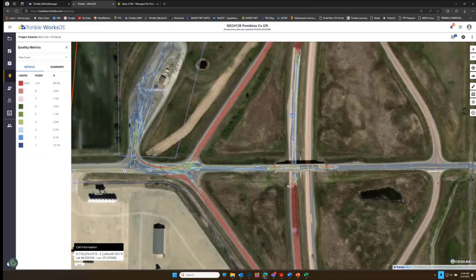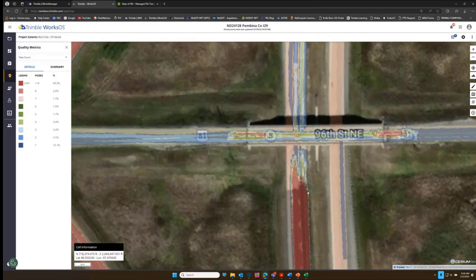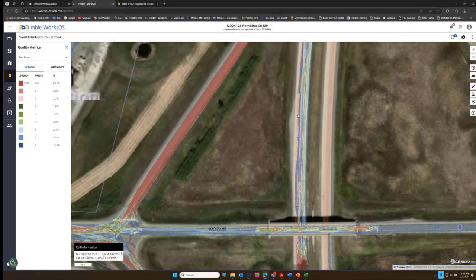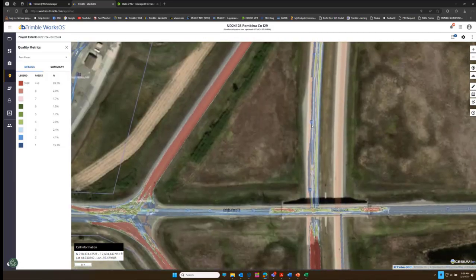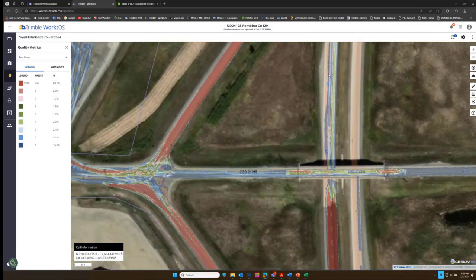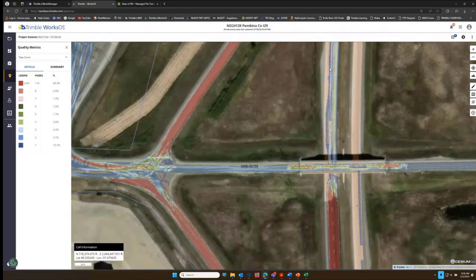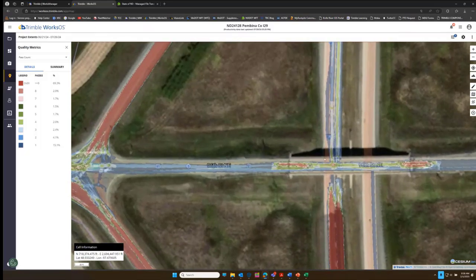And we see our IC data, and you can see wherever the asphalt ended and concrete began, there's less compaction effort, obviously, because they're just kind of rolling past it. And we'll take a look at that. Also under a bridge, right? GPS isn't going to work, so you're always going to lose data. Even if this was asphalt under here, you would lose that data no matter what.